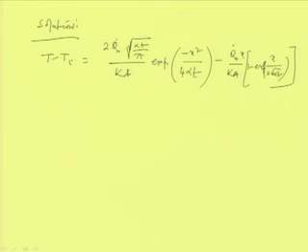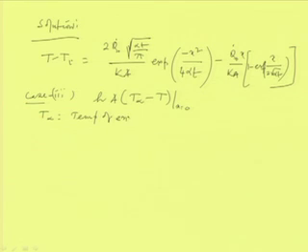Okay. Now, case 3: the variable boundary condition, where the heat flux is varying. How is it? At x equal to 0, h is the convective heat transfer coefficient, A is the surface area, T infinity is the surrounding temperature, minus T, the temperature of the solid body at x equal to 0. T infinity is the temperature of the environment, and this should be equal to minus k A into del T by del x at x equal to 0.